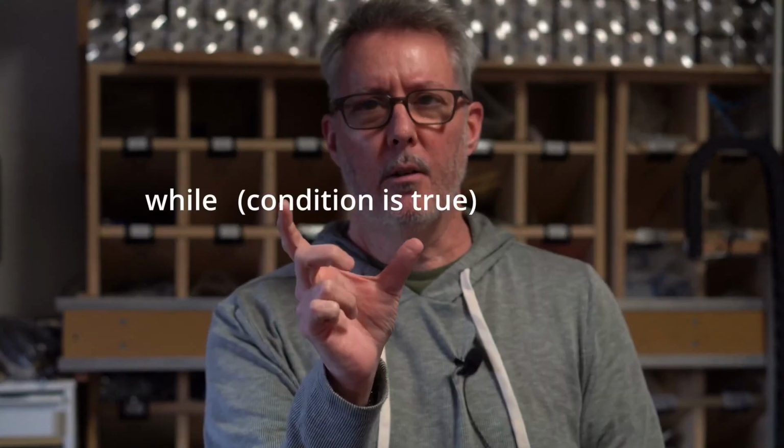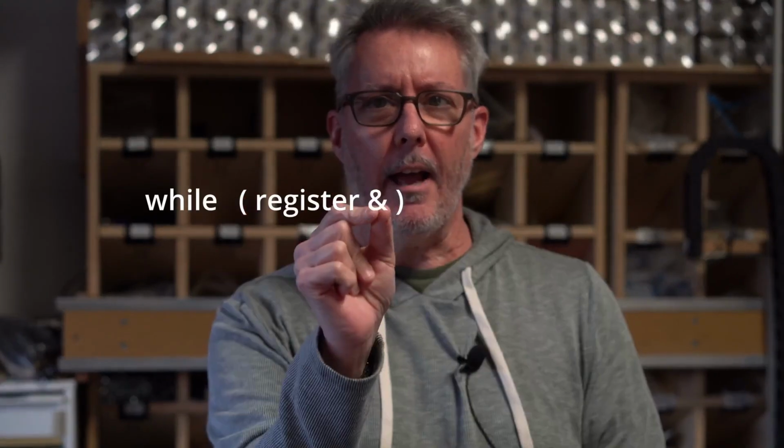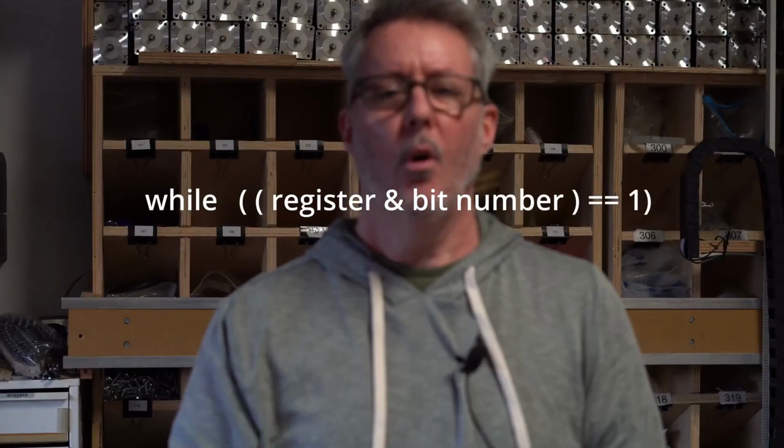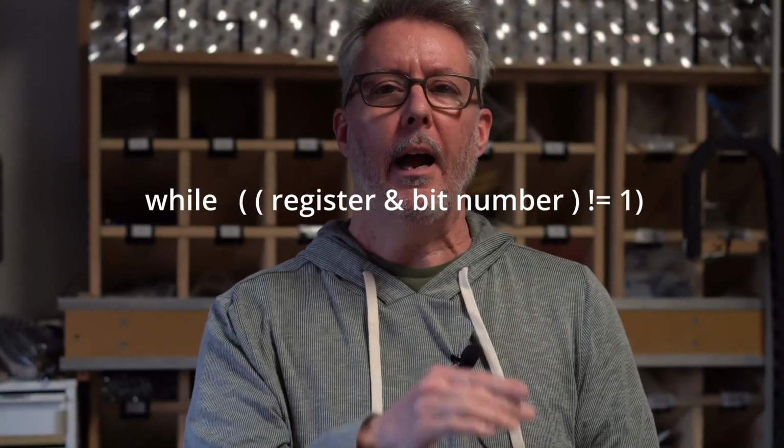And the condition within this while loop is the register and the AND sign and the bit, and whether that is equal to 0 or 1, or whether that is not equal to 0 or 1, however you want to represent that condition. A scenario where you would use this, testing whether a bit is on or off, is when you enable something inside the microcontroller, let's say the analog to digital converter. You will have to enable certain aspects of that converter. And once you set something to be enabled, the microcontroller needs some time to make sure that particular feature is enabled.